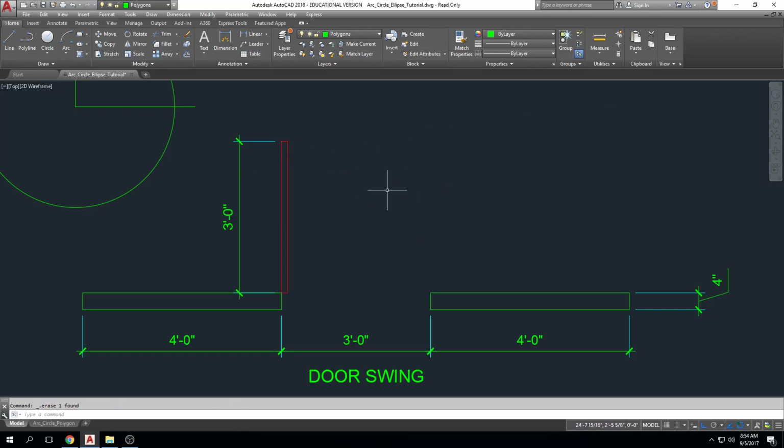Okay, and I think this is another where it gets tricky, right? Start, center, end. Well, start, center of the arc, end. No, it's center of the circle that generates the arc. Okay, so we have our start, click, center, click, and then kind of by default, end, click.